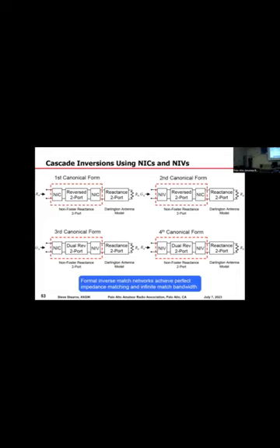So here's some pictures. We have a Darlington antenna model on the right. Here's four ways to do it. I call them canonical forms, 1, 2, 3, 4, four canonical forms. And they all have the antenna and antenna impedance model as a reactance two-port terminated by a resistor.